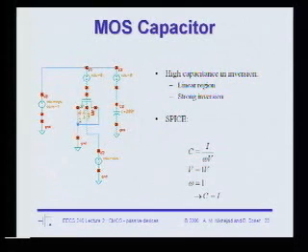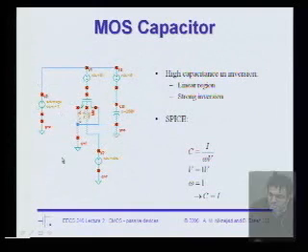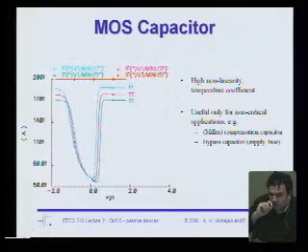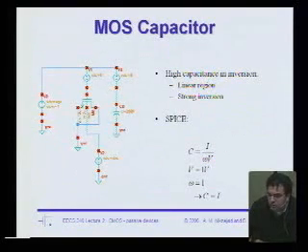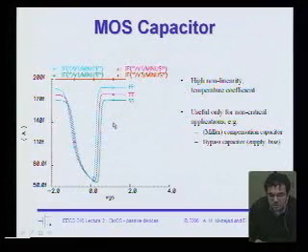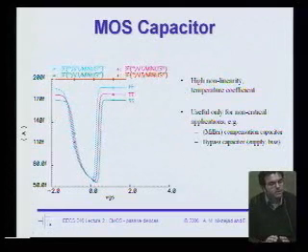Another way to do it is you just run an AC simulation, and in this simple AC simulation, you can see that the capacitance just works out to be the current going into this source. You can verify that. It's very simple. And so I can now measure the capacitance as I vary VGS and possibly VBS and see how much that capacitance varies. And this is the result for our class transistor. Just to make sure that the simulation works, I put down a known capacitance of 200 femtofarads, and then I ran the simulation. This is always a good idea. I'll recommend this in general.